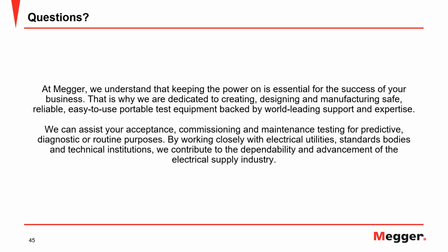The other thing is, if you do have that kind of condition and you're doing a narrowband DFR, we can help you. You can send us the measurement and we can help you on the analysis, right? And look into our database, depending on the type and manufacturer of the bushing. That is something that we always assist our customers with if they don't have something to compare against.